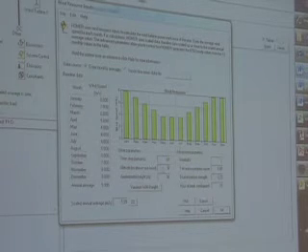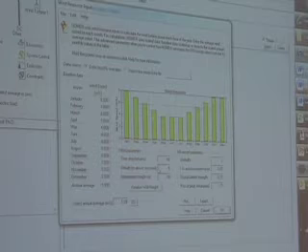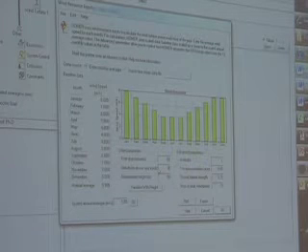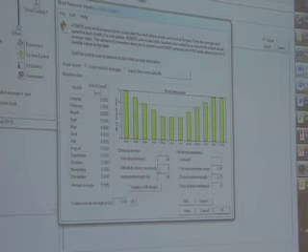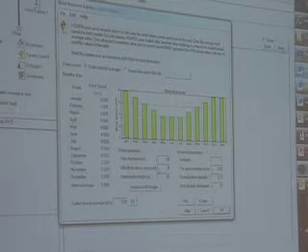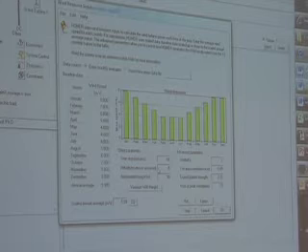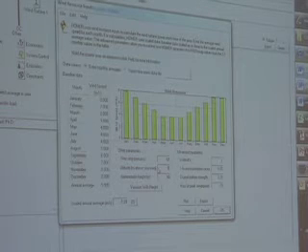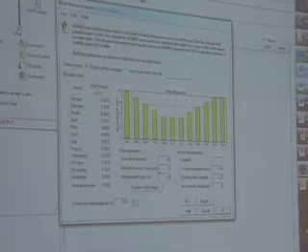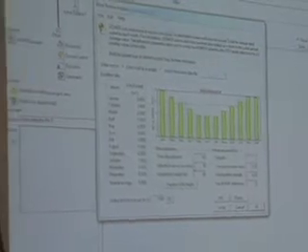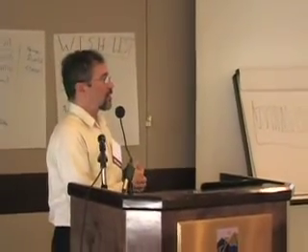We also have altitude here. Somebody asked about temperature. We really should have temperature. We ask for temperature and use it to correct the efficiency of the PV, and we should do that for the wind as well. But we don't in this version, we will in the next version. But you can do your own calculation and adjust the altitude, because that has the same effect. It's just the air density.